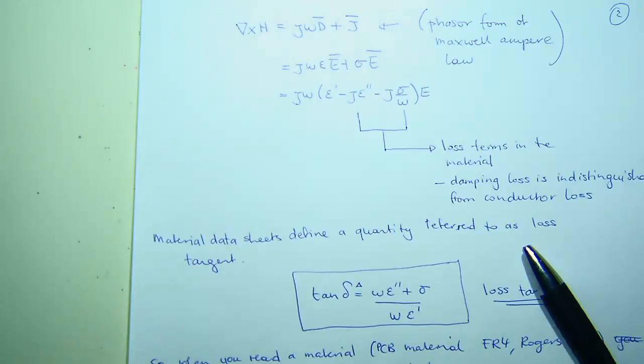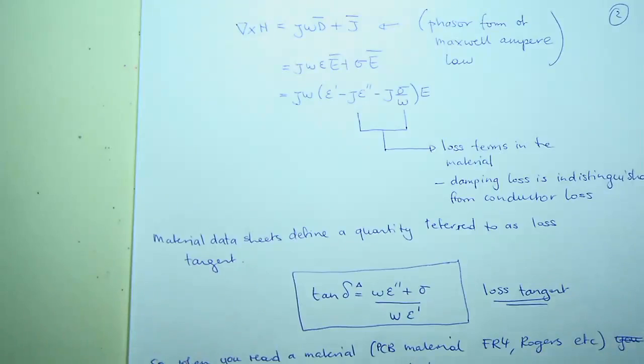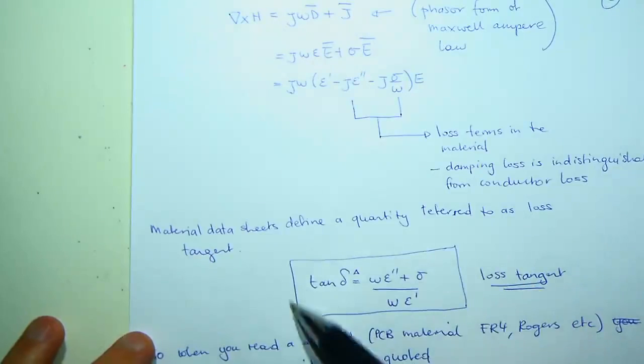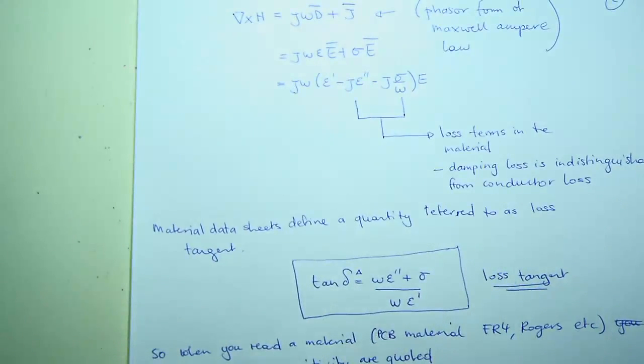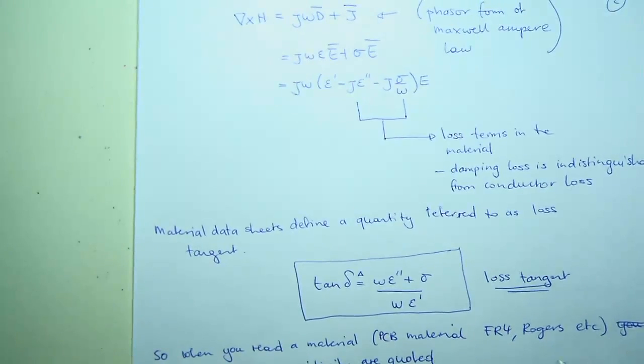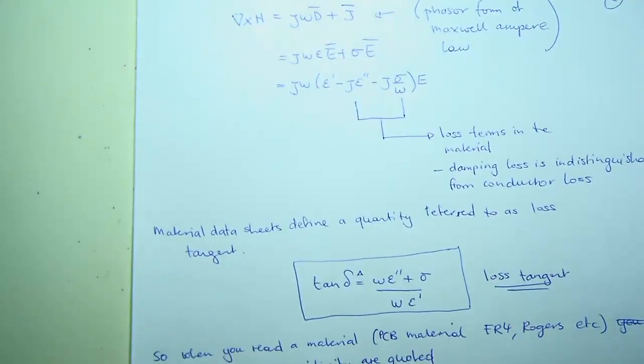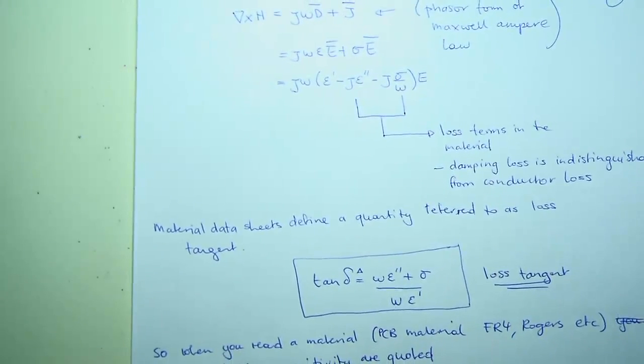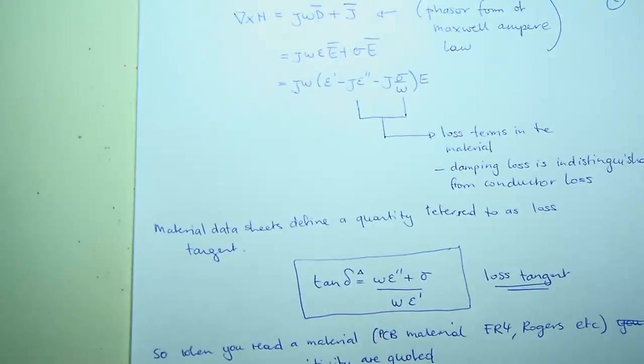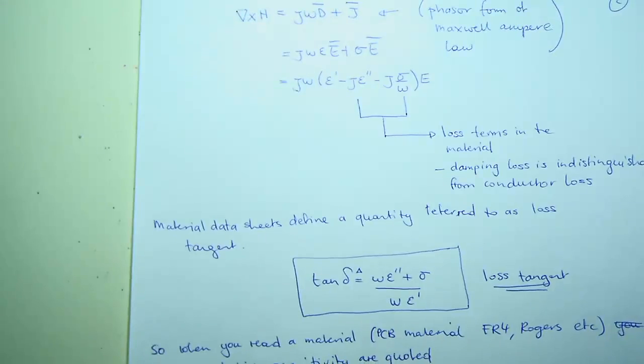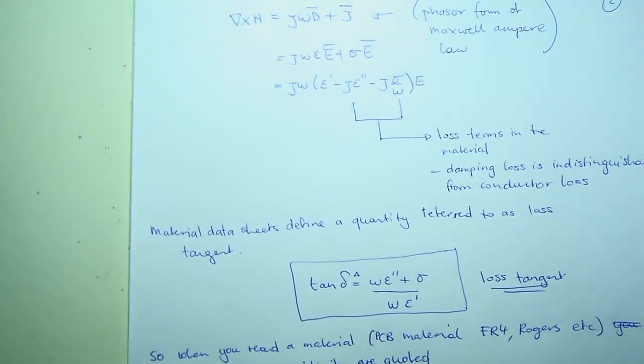Right. So that's the reason why I'm telling you this. It's not that I just want to torture you. There's a reason, right? So what you do is you find the loss tangent, and depending on the material, and you've got the relative permittivity, you can also work out what the complex permittivity for that material is for a specific frequency.